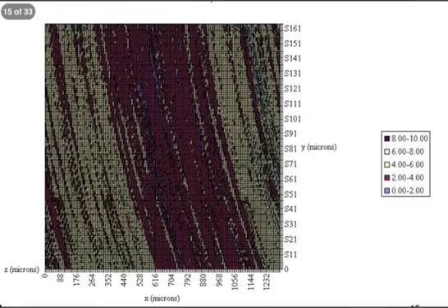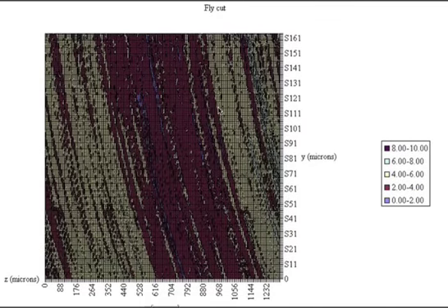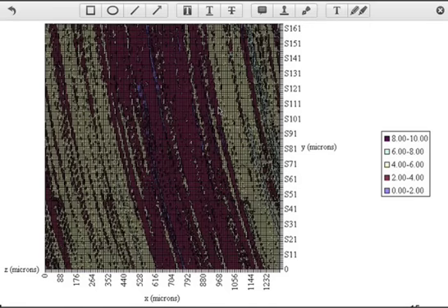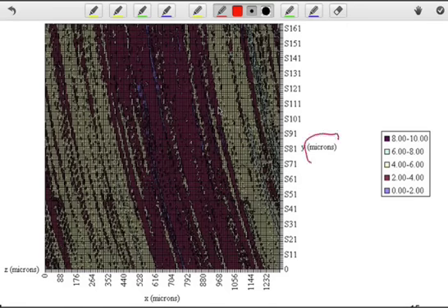Here's an example of a surface. Note the scale. The scale here is microns. So we've got X and Y, and we've gathered data across the surface. You can definitely see the lay here as the tool, which is a fly cutter in this example, and you can see the magnitude of irregularities on that surface.